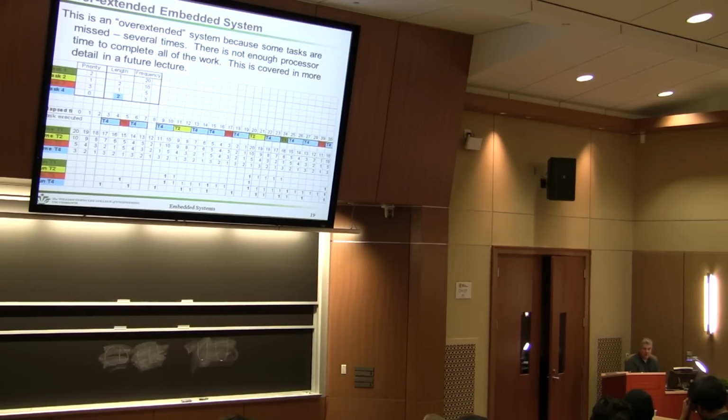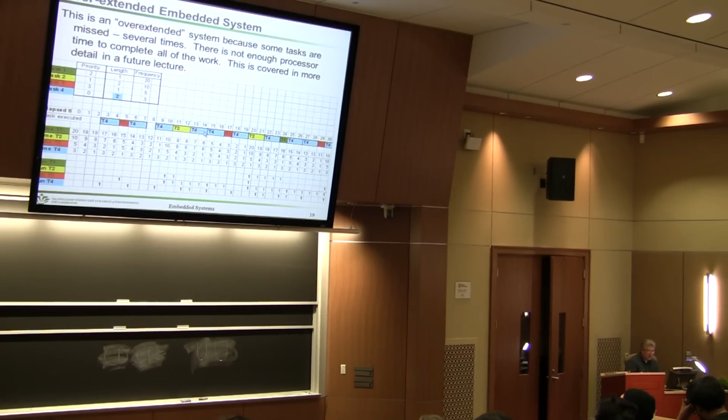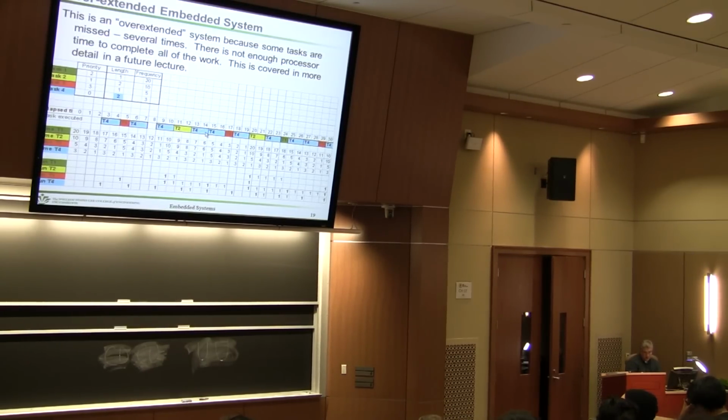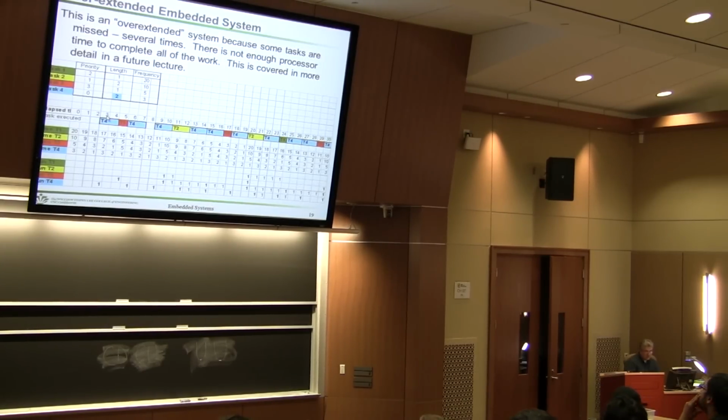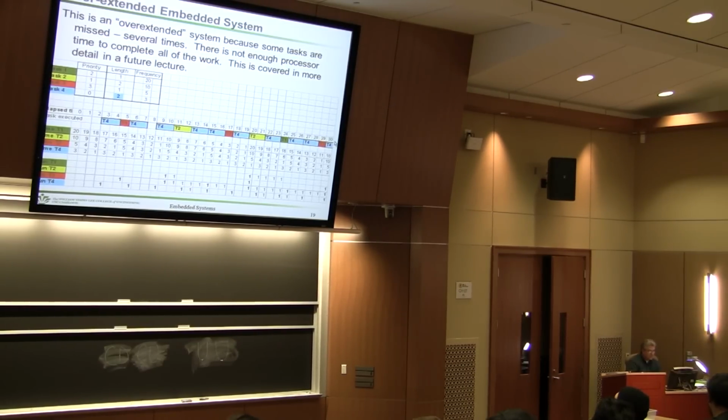Now, is that going to cost you more money? Yes. But in many cases, remember the amount of time that this takes to run is going to be reduced. Let's say if you double the clock, these tasks will take half the time. And, oh, by the way, these are just timer ticks. They're not necessarily milliseconds, it's a certain frequency. So this would pretty much stay the same.